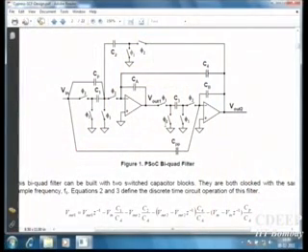Because the value of V out 2 changes only when we are in phase phi 2. And in phase phi 2, these two nodes are connected. And in phase phi 1, V out 2 remains constant, and anyway this node is disconnected. So it doesn't have any problem. And phi 1 is only a matter of transferring to the C3.